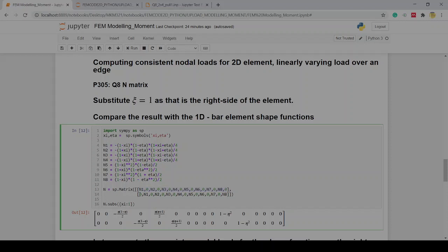And if I look at the even positions, these help to interpolate the Y field, things that are in the Y direction. That is the nature of how we decided to assemble things. Essentially, that is the way the two vector fields, the interpolation of the displacement field in the X direction and the displacement in the Y direction, are split in the finite element method for the two-dimensional case.